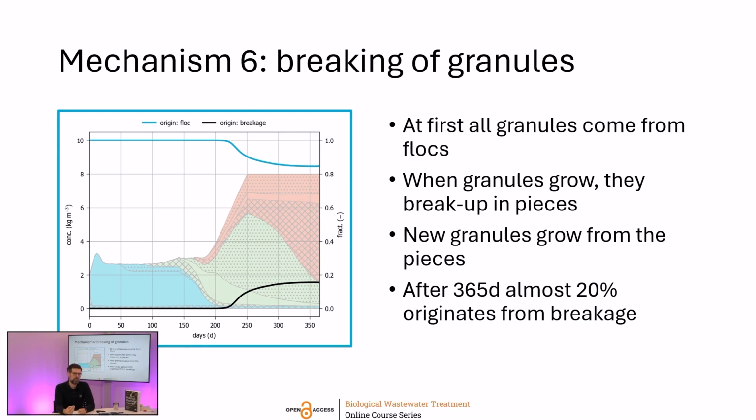process. And what we already saw in practice, if you cut granules and you look at them under the microscope, you often see that there's like a shell of an old granule in the core of the granule. And what really helps, and we try to simulate it a little bit, is that if you have a granule that breaks up, then all those pieces of the granule are new seeds for new granules, because new biofilm will form around that old piece.